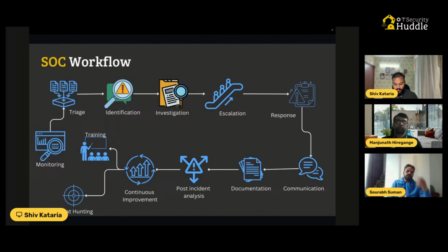Then you need to know, if we do this type of response, what could be the consequences. So let's suppose you find one HMI infected and you isolated everything, then that can leave your complete operation department devoid of viewing anything. So that could end up in another type of attack, that could be the loss of view attack. So the response part is the most critical.